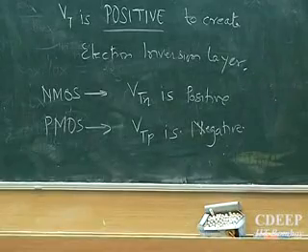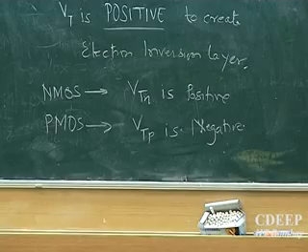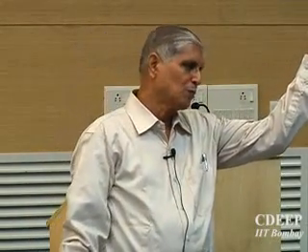Minus of minus is what? No, you said it the same, so I only retorted back. No. Qs is minus epsilon Es irrespective of what Qs value is. This yes, direction will change. That's it. The electric field in this direction will change if the polarity changes. So Qs is minus epsilon S Es, valid for either P or N. That has nothing to do with what kind of substrate I create. Gauss's law does not say which charges. It says Qs is minus epsilon S Es. Is that clear? Independent of polarity of the charge.